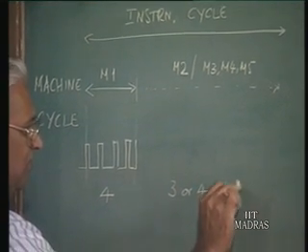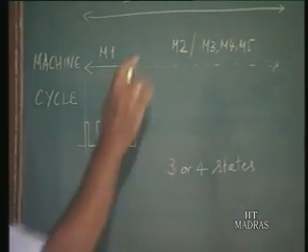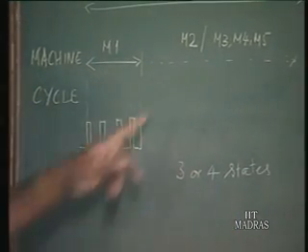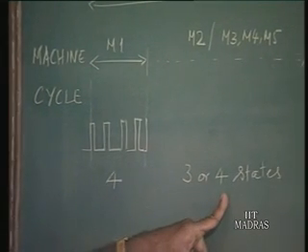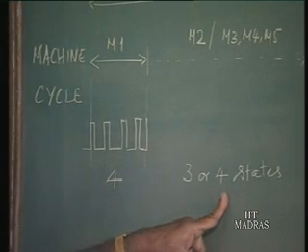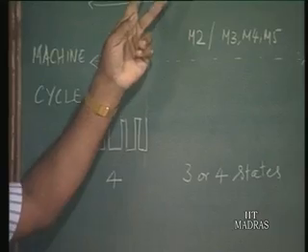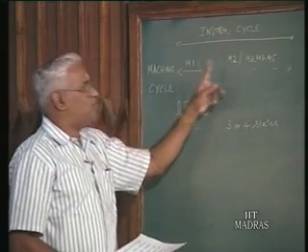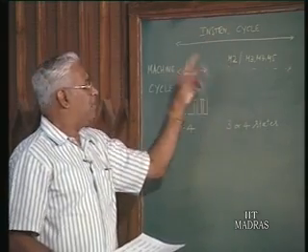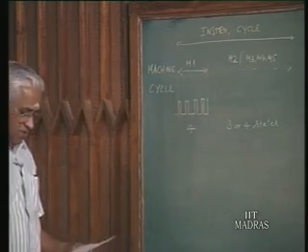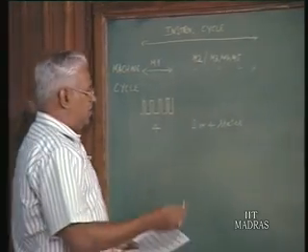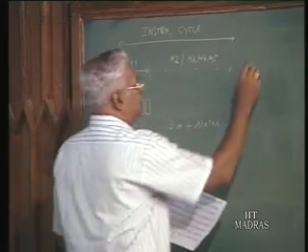That is what it is given, each of the remaining machine cycles, that is M2 to M5, will consist of either 3 or 4 states. Okay. And an instruction cycle consists of a minimum of M1 and M2 and a maximum of M1 up to M5, that is given. Then of course, the CPU's clock rate is given, we will make use of it later.